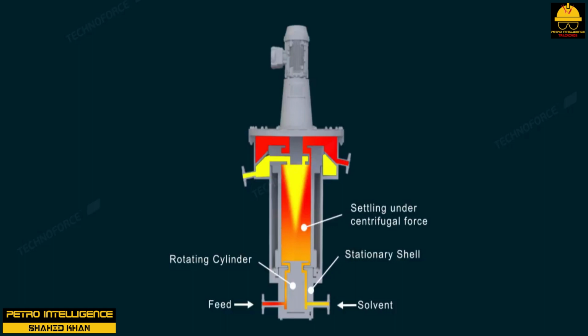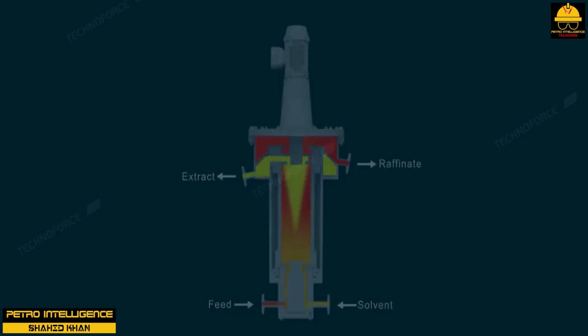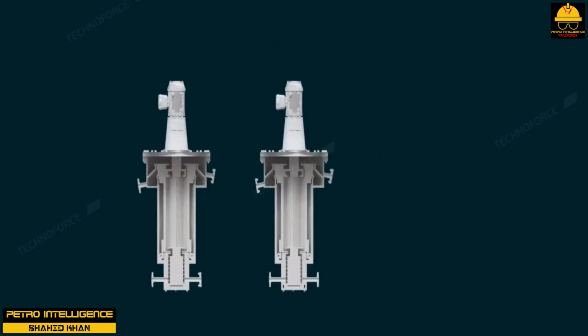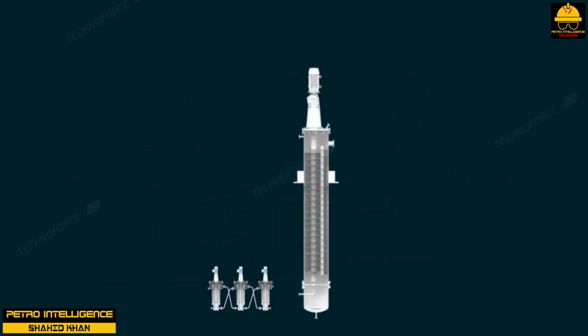In effect, such an arrangement is an attempt to use several stages to accomplish the separation that could be accomplished in a single stage with perfect mixing by remixing the materials again and again. A more efficient approach would be to use a countercurrent flow arrangement, introducing the solvent at the opposite end of the chain of stages from the feed. In such a system, the feed to each subsequent stage is contacted with fresher solvent than was in the preceding stage, thus providing a more efficient operation. Such countercurrent flows are almost always used in commercial equipment to provide greater efficiency.